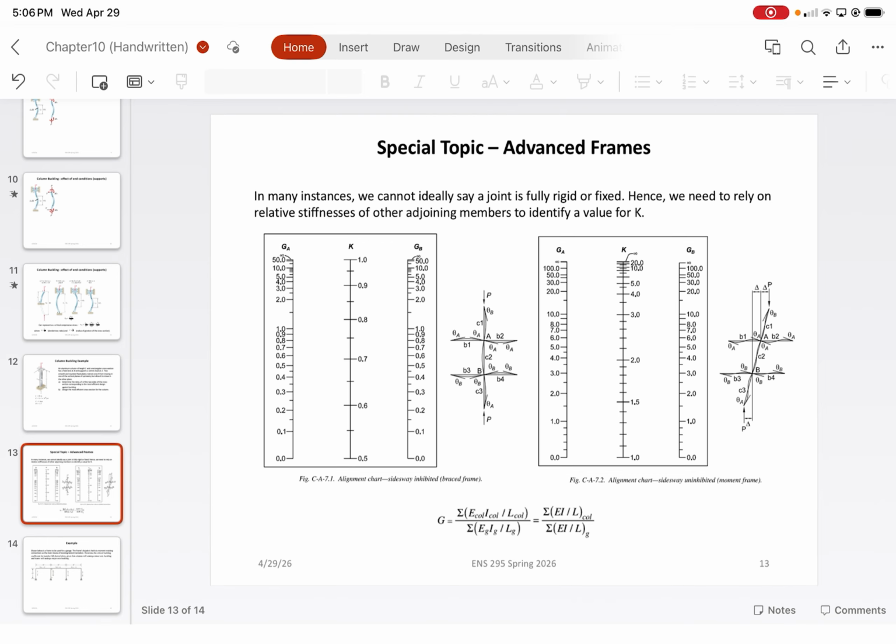The two beams are going to provide some type of torsional or rotational resistance, right? But not to a point where it's entirely fixed. Because of that, we have to use these tables, which have been iteratively developed through experimental data to determine approximate K values which best define the behavior. So it's basically just accounting for the stiffness at joints instead of assuming an ideal stiffness.